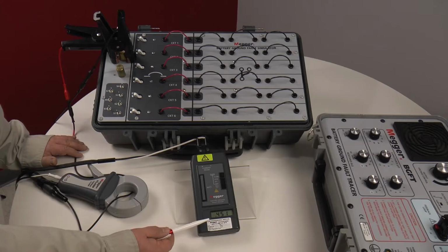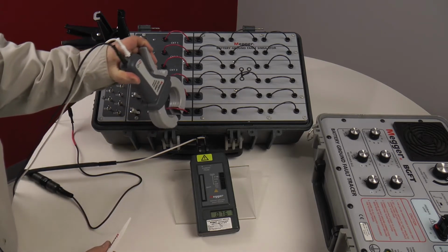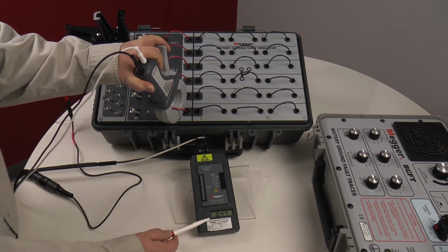If the majority of the fault current drops when adjusting the capacitance, then there is a large amount of leakage current on the system, and we need to take an extra step to verify we are tracing the correct path. In this case, we note our total fault current is 0.451. We go to the panel and find what circuits have fault current.